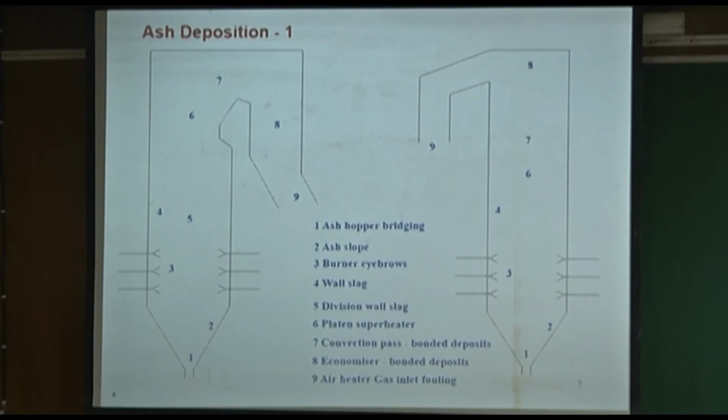The boiler manufacturers will tell you this is the way to manage the boiler. There are some wall blowers which are fixed, using either air or steam blowing. There are some retractable steam blowers which can go in, inject the steam, and then clean, and get out and clean the opposite side. That all depends on their maintenance.